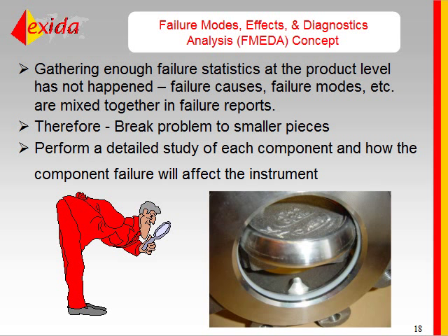I'm going to look at an actuator and a valve, and in the actuator, for example, I'll look at every structural member, every spring, every diaphragm, every piston, and at that level, I have good failure rate and failure mode data on the components.